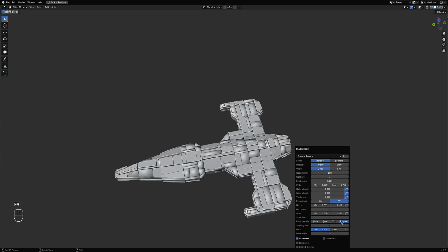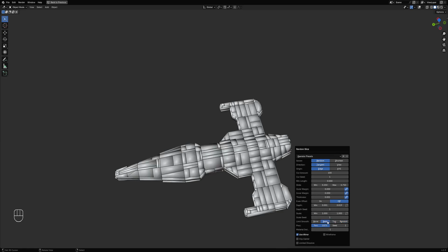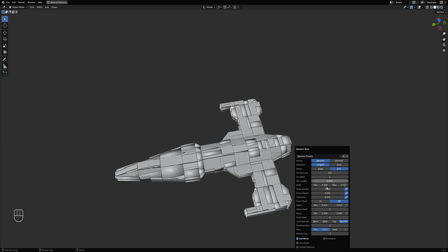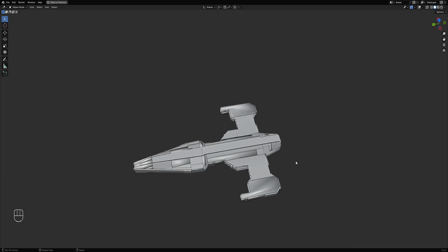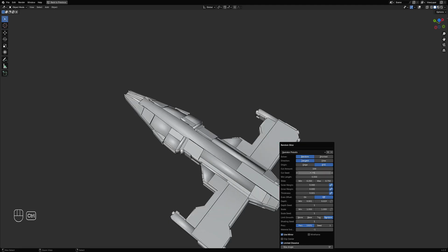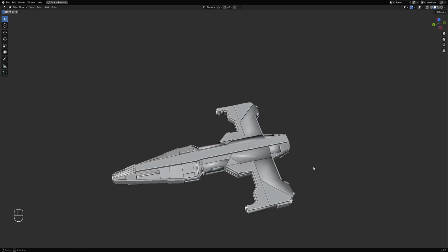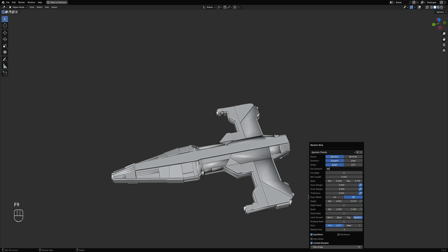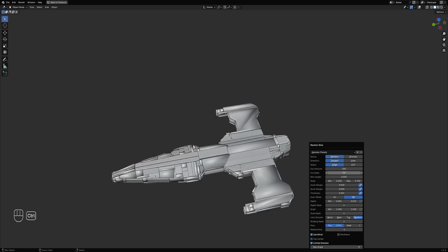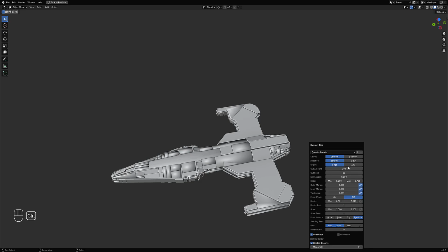you can play around with randomized shading now and also use base top, smooth by angle or flat. And let's just use random and source the direction of the cast using just the literal XYZ direction. And then you can also limit the solve, basically merging the faces based on an angle threshold instead of creating the cut per face. You can increase this, create your details here, XYZ.